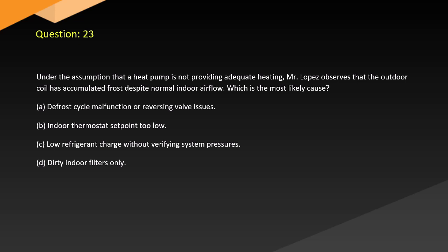Question 23. Under the assumption that a heat pump is not providing adequate heating, Mr. Lopez observes that the outdoor coil has accumulated frost despite normal indoor airflow. Which is the most likely cause? A. Defrost cycle malfunction or reversing valve issues. B. Indoor thermostat set point too low. C. Low refrigerant charge without verifying system pressures. D. Dirty indoor filters only.